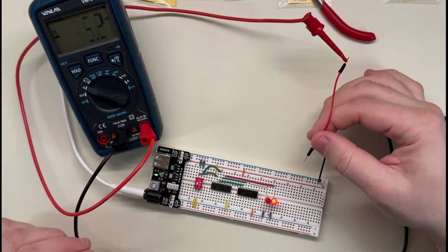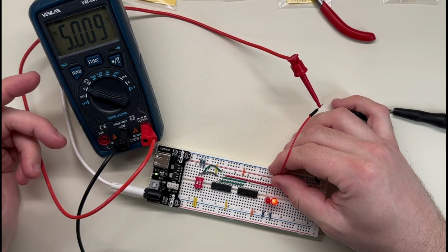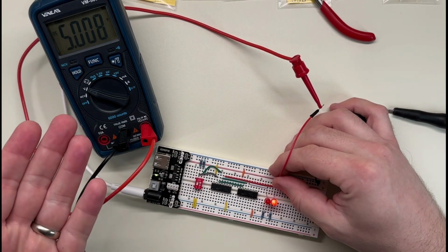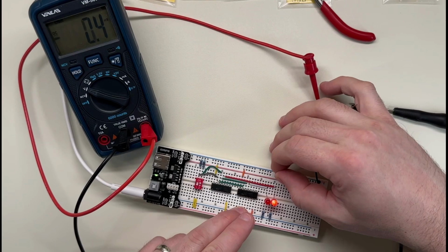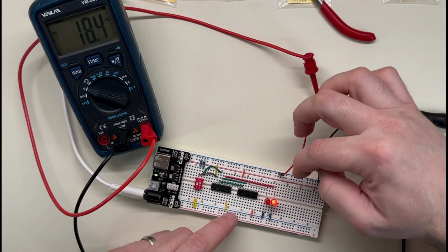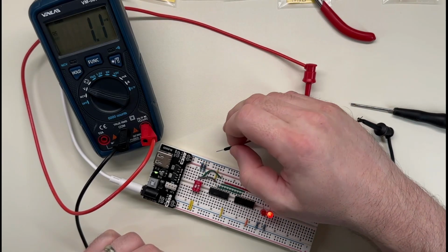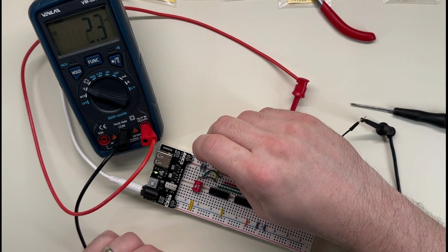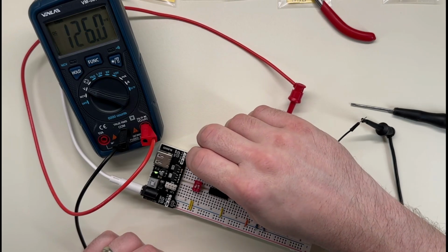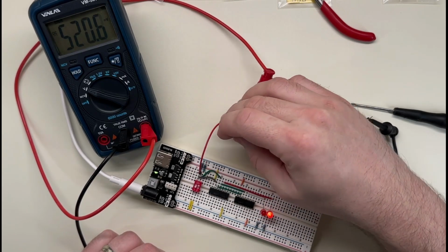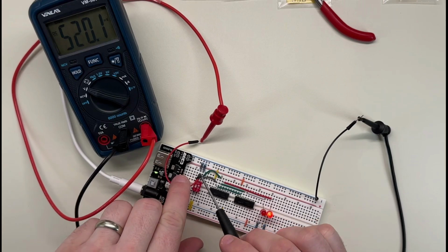So I think the first thing to do is check the plus side, right? It reads 5 volts, almost exactly 5 volts. Seems pretty accurate to me. I guess that's the voltage regulator doing its thing. If I put this on the minus, it of course reads nothing, because minus and minus. All right, so we have one switch off and one switch on. If I check the off side, this one, the current should be going through our pull down resistor, which is the one right under the wire here, this one.